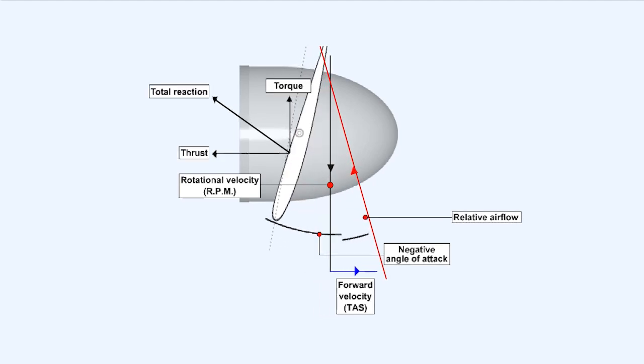Propellers which can have their pitch angle made even more negative are known as fully reversing propellers. As the power lever is moved further rearwards into the reverse pitch range, the blades move into the negative pitch position. The reversed total reaction produced now increases.